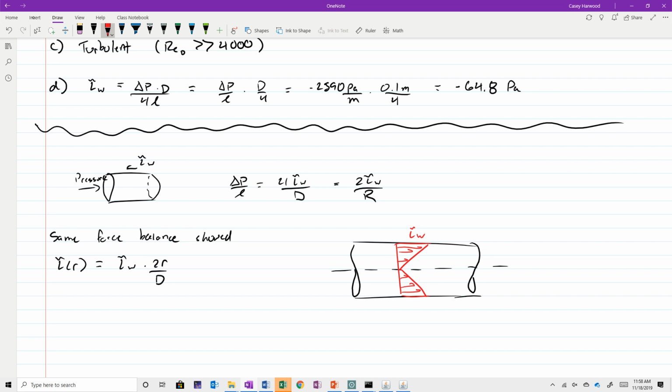Now what we did do in laminar flow is we said, all right, we know something about the way that this tau, the shear stress, is related to the velocity gradient for a Newtonian fluid. And from there, we were able to leverage that knowledge to come up with a differential equation that looked a lot like a partially solved Navier-Stokes, and we integrated that once, and we got a velocity distribution.